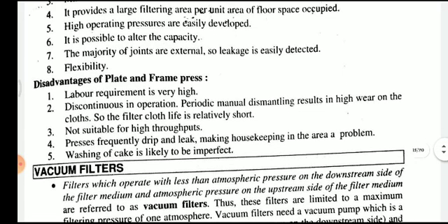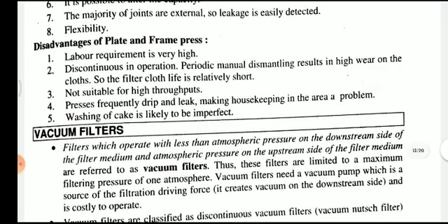Disadvantages of the plate and frame press: labor requirement is very high, it is discontinuous in operation, and periodic manual dismantling results in high wear on the cloths. So the filter cloth life is relatively short. It is not suitable for high throughputs.